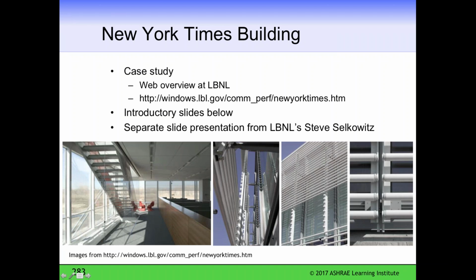You have horizontal bars below the desk height. You have an open area in this third picture on the right. When you're seated at your desk or walking around, you can see out the window, but above that, you have horizontal external shading that effectively is blocking the direct beam light on the windows and reducing the cooling load.